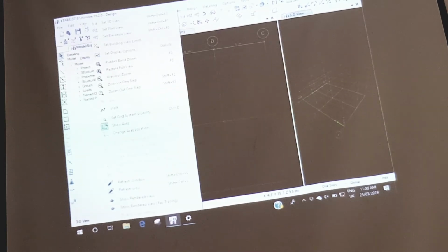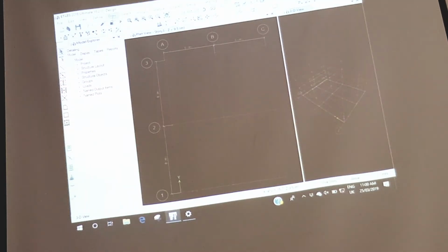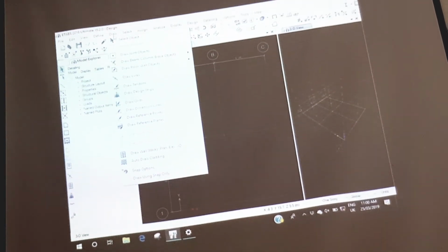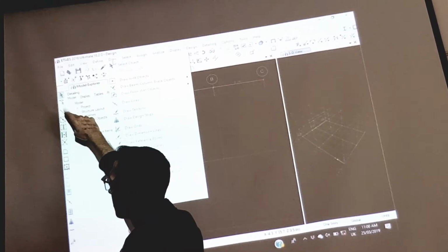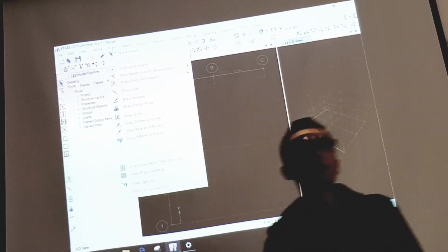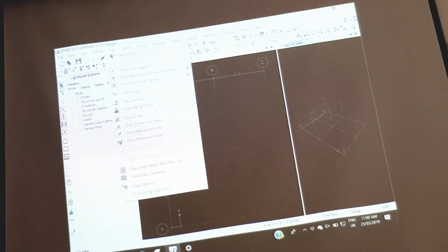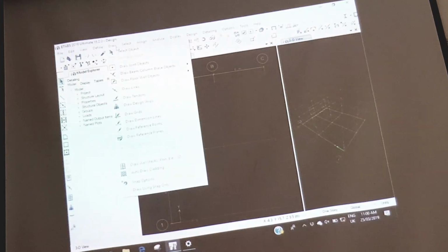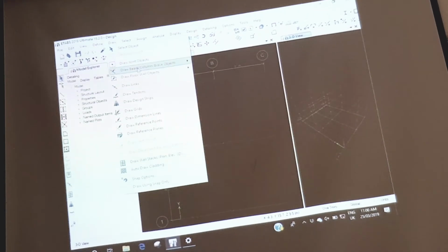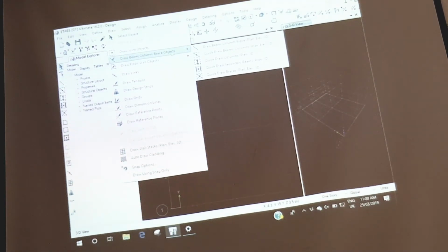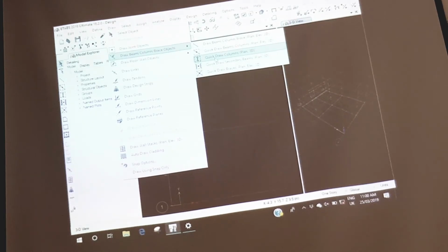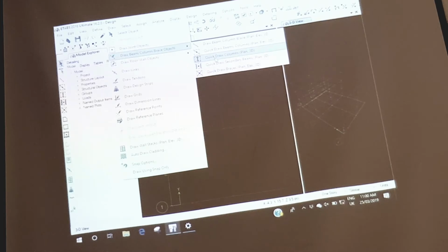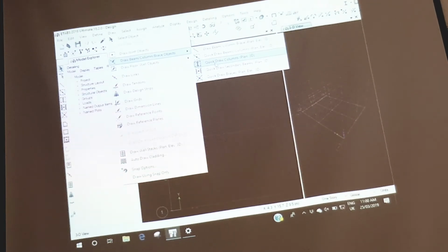For example, you can go to draw, or you see that you have one vertical tab over here. These are the ones you can draw quickly. Okay. So let us go step by step. Go to draw tab at the top. Draw beam column. First of all, you are going to start with columns. You have to define your columns. So quick draw columns over here. Click on quick draw.